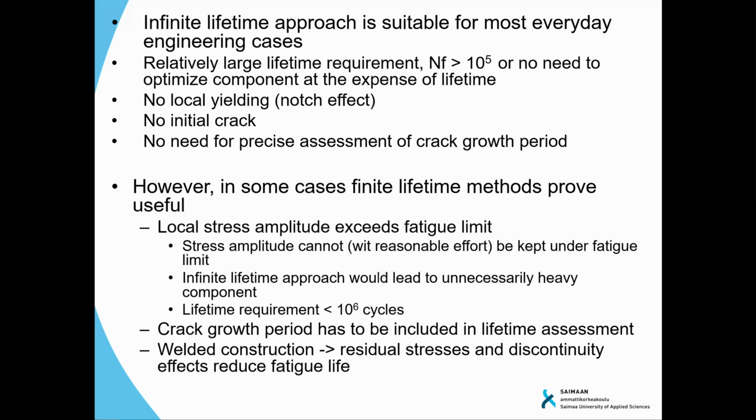Yes, basically. And also, it's not applicable because it cannot predict the crack growth. It cannot be used for precise assessment of the crack growth period. If you want to utilize the lifetime which is remaining after the initial crack, then of course you would need to use fracture mechanics. This doesn't apply. That is also common sense. So therefore, in those cases, you will need to use finite lifetime methods. The rest of the slides cover that topic, but we don't go too deeply into how to use those methods.